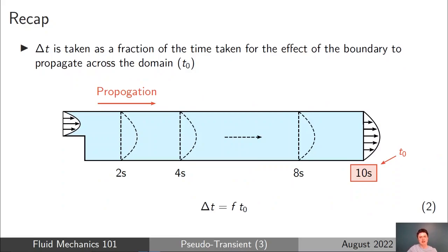So how do we specify the pseudo time step size? Well, the first approach would be to do something similar to what we did with relaxation, where we just arbitrarily choose a value of the pseudo time step. And that approach could work, but it doesn't generalize very well to lots of different CFD cases. And what we'd actually like to do is to get the CFD code to specify and calculate the pseudo time step size automatically. And that's been the focus of the past few talks.